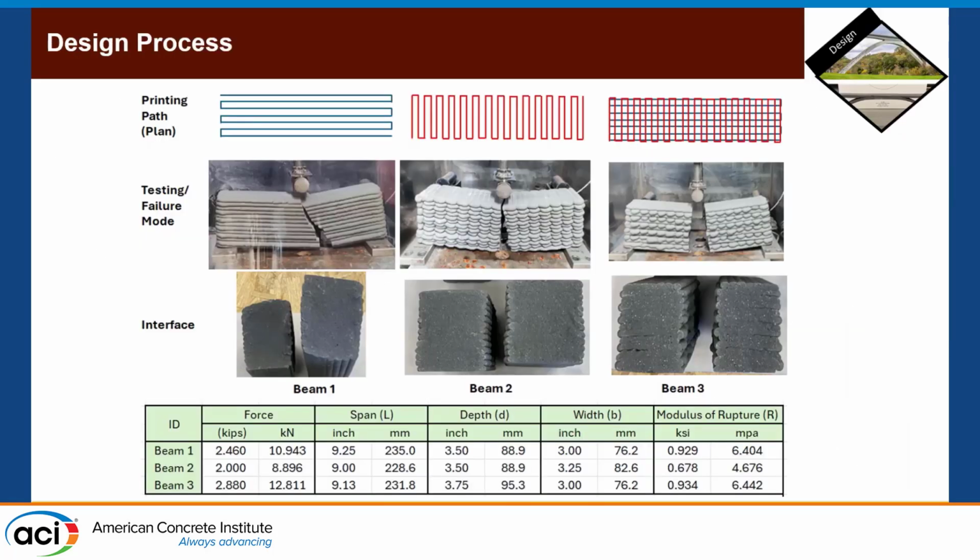Design-wise, we did a lot of work on printing path. So we have one specimen where we printed longitudinally, filament upon filament, to achieve 3-inch height and 3-inch width. We also printed transversally, so when you load it under 3-point bending, it will be perpendicular to the layers. And we also printed